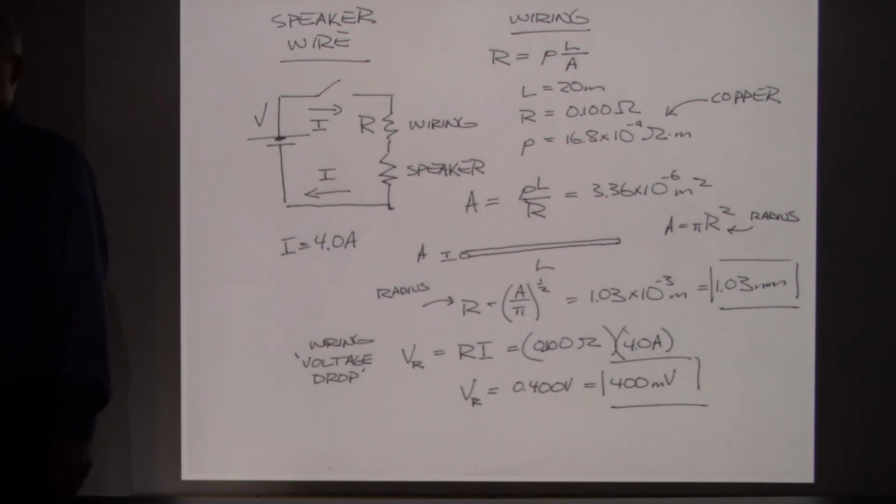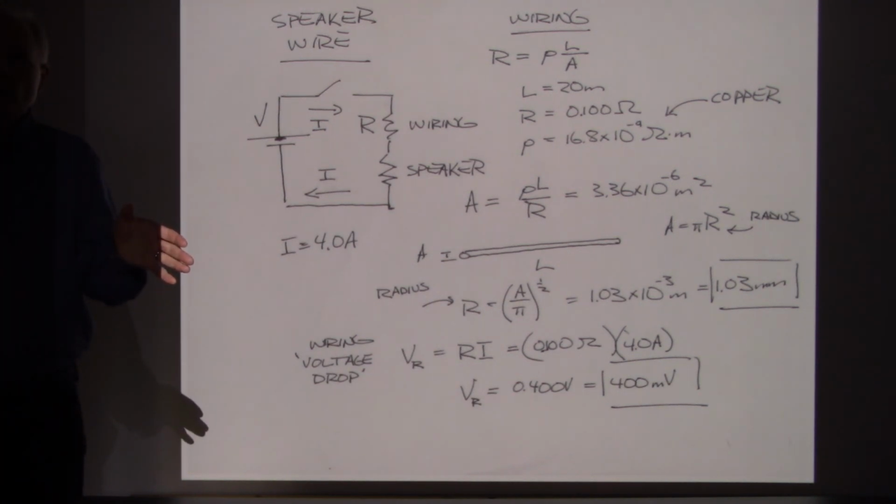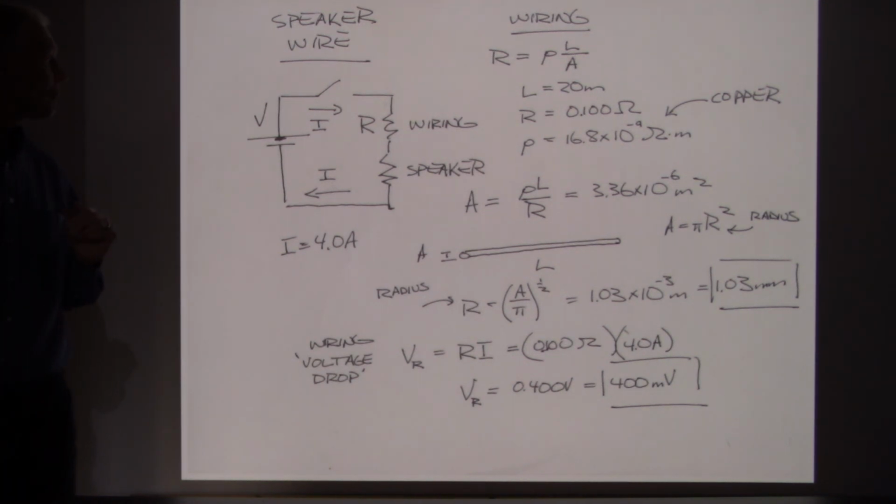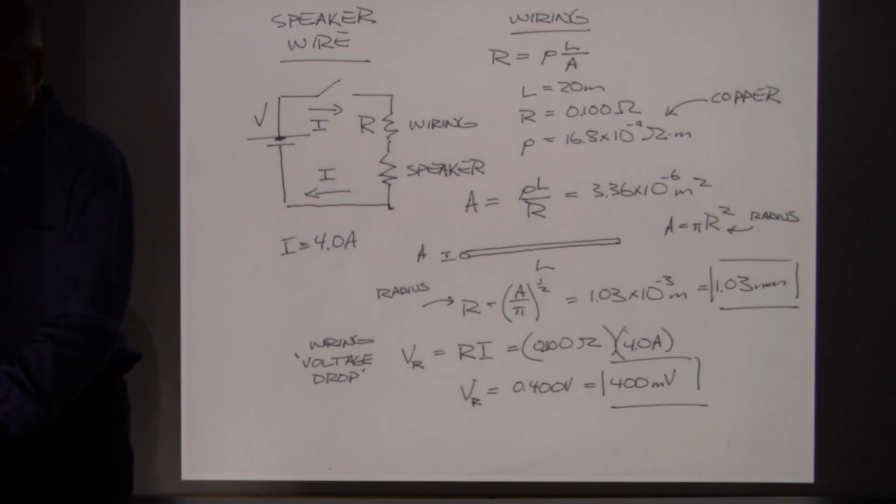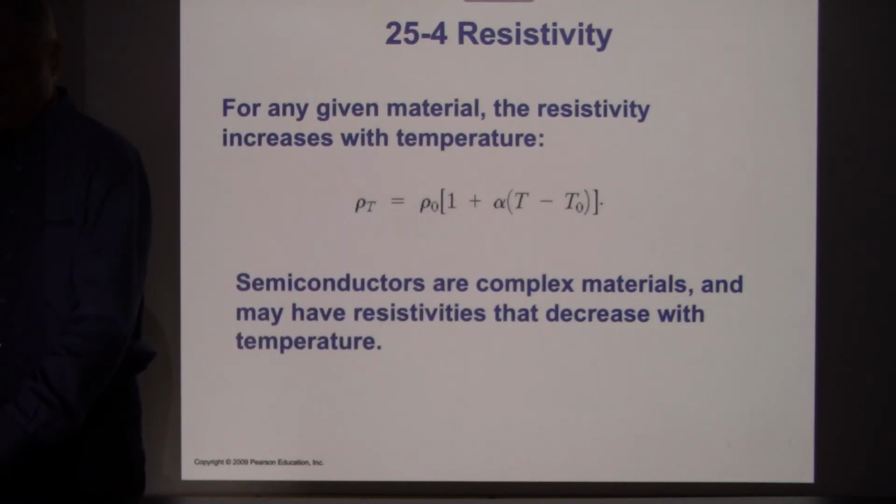So that's the way we would run the numbers and find out, are we going to end up using a lot of our energy in the wiring, or is most of the energy going to reach the speakers? And it sounds like with the setup we've got, with the numbers we were given, most of that energy is going to reach the speakers.